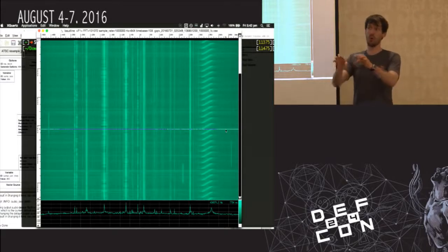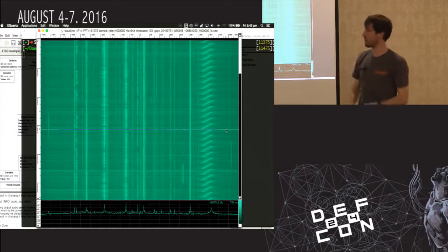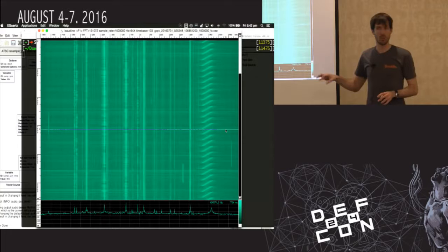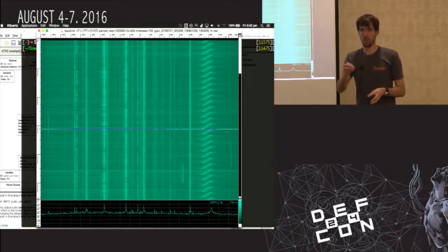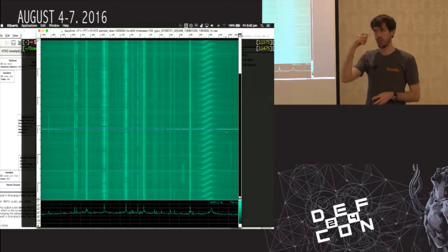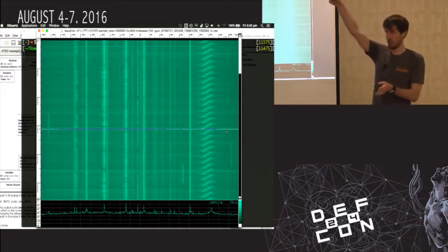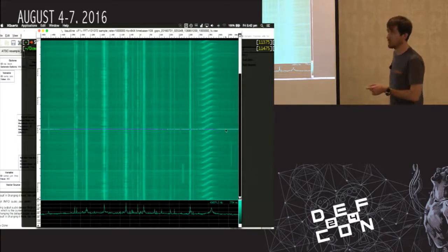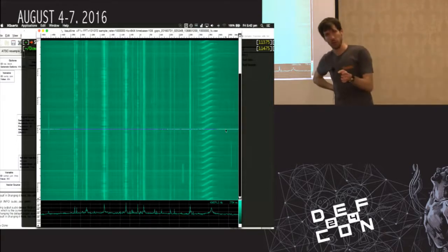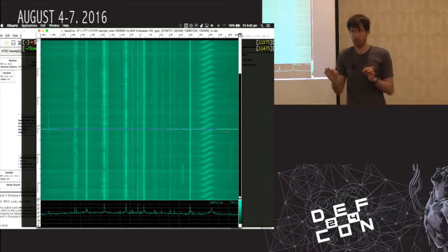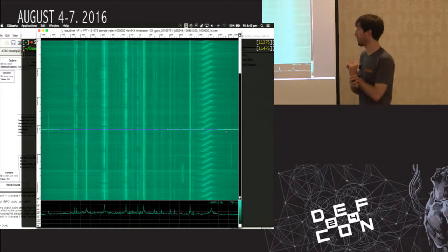But because you have no control over the transmitter, usually, if you're lucky, the transmitter is locked to GPS. So if you can get an SDR that accepts an external reference input, you can get a GPS DO, GPS disciplined oscillator, that will output 10 megahertz that's disciplined by the atomic clocks on the satellites, and that will bring your sampling rate into alignment with the transmitter, which is what you need to then very accurately process the information and extract Doppler information as well.